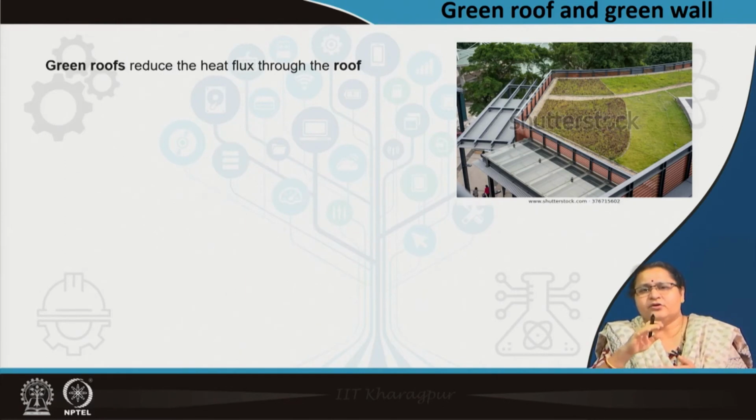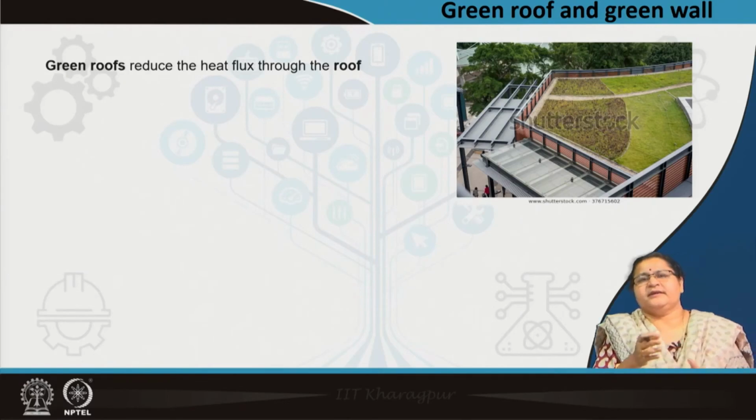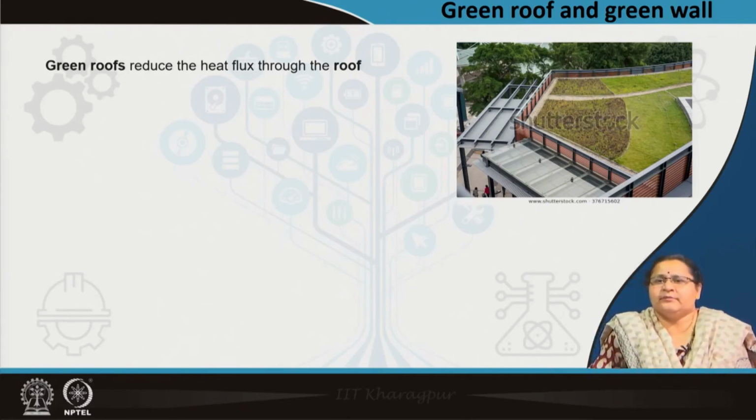So, you have to allow a good thickness for having a green roof. So, automatically it reduces the heat flux through the roof, but at the same time there are multiple things happening in between the layers. So, we have to be very careful to recommend a green roof just for the purpose of insulation. Yes, it replaces the amount of green you are losing at the ground level and you are replacing that on the top maybe partially, but it does not mean it is giving you a thermal insulation, and that is why you need to do green roof.